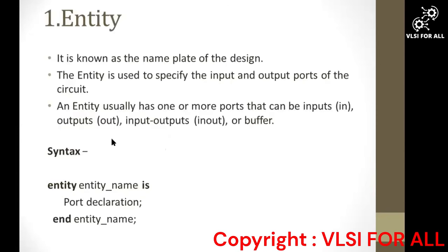So what is entity? Entity is known as the nameplate of the design. It is the naming of a design. It is used to specify the input and output ports. Within the entity, we specify the input and output ports of our design, and there can be one or more than one input and output ports, and a port can also be both input and output. So this is the syntax of entity.